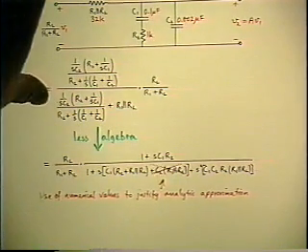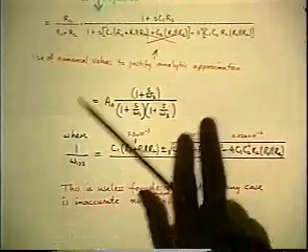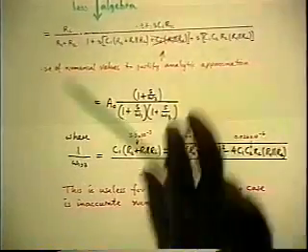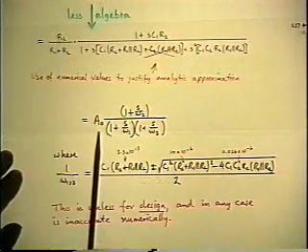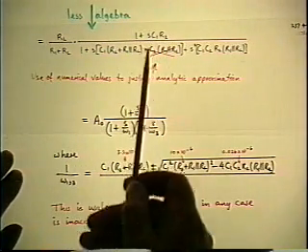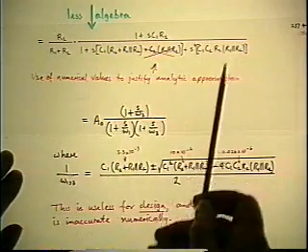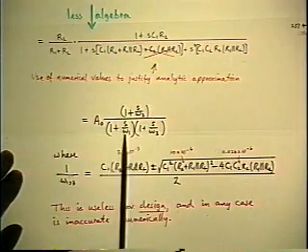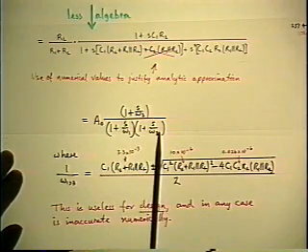Okay, the final result now, already you can see from this expression, is that we have a flat gain coefficient in front, and we have a linear function of s in the numerator that immediately defines a 0, and we have a quadratic function of s in the denominator, which means we will get two poles. So I've designated them omega 1 and omega 3.